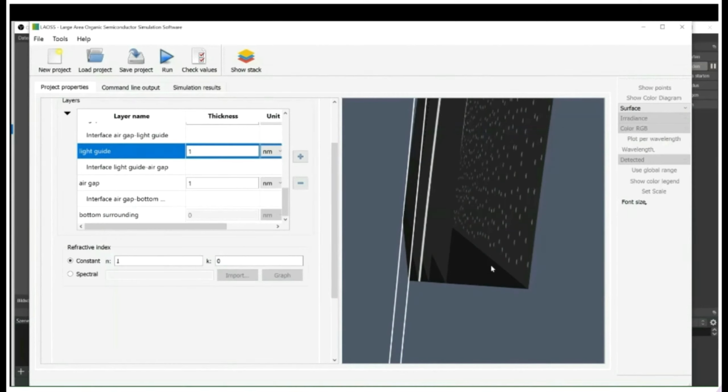In fact, any interface, including the formerly plain or smooth ones, needs to be defined with the appropriate curvature, which in some cases can still be achieved via an XYZ topography. More complex topographies like the bottom roughness or the brightness enhancement prism film, however, can no longer be represented unambiguously in this way, but need to be provided as a 3D surface.